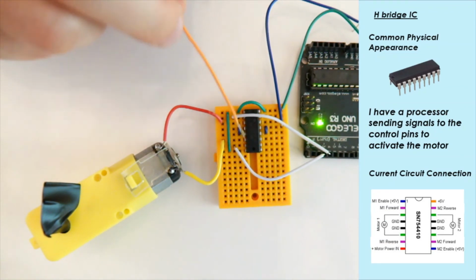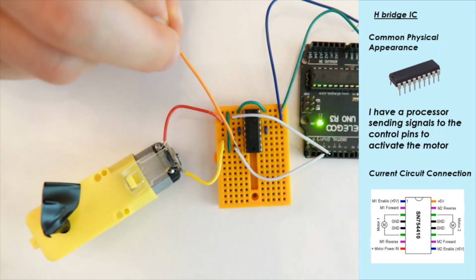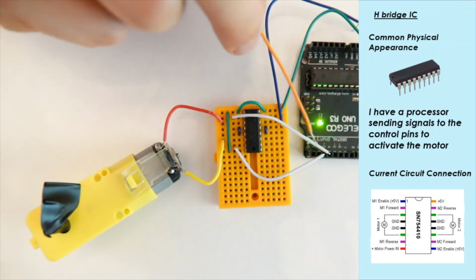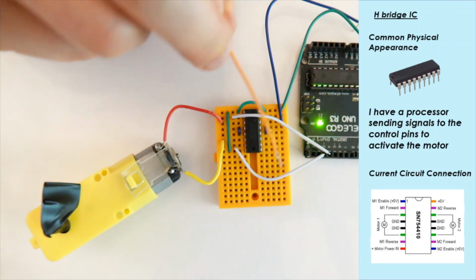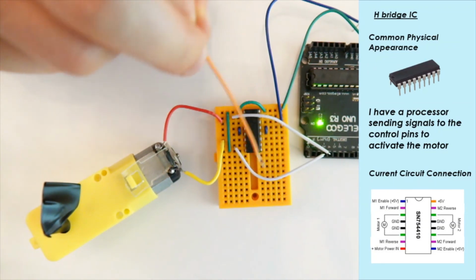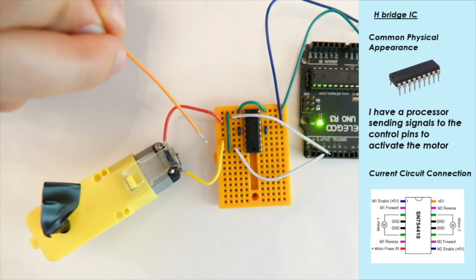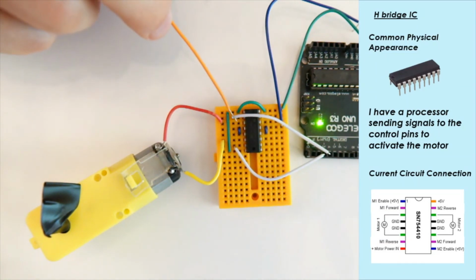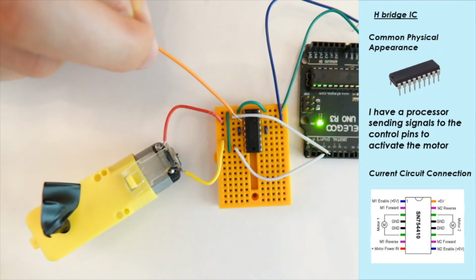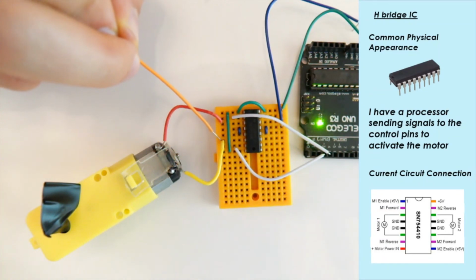These white pins, which are our motor forward and reverse, so our actual connection signals, are connected to the processor. This is programmed to output 5 volts and 0 volts alternatingly between these two wires to make the motor reverse and go forward. So this is alternating all the time. Then we've connected pin 3 along this rail, so you see pin 3 across the rail, to the first pin of the motor. The second one comes out further along down here.